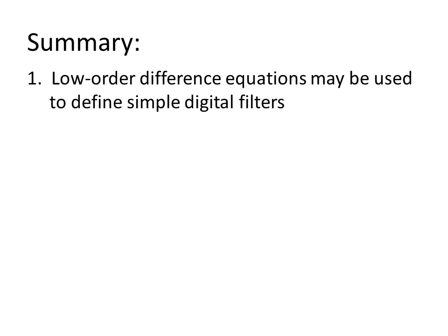So, to summarize the main points of this lecture, it's very nice to know that low-order difference equations may be used to define simple digital filter types, such as the low-pass, high-pass, and bandpass filters. Using just a few operations, we may implement useful processing tasks that we typically define in the frequency domain as passing or blocking different ranges of frequency.